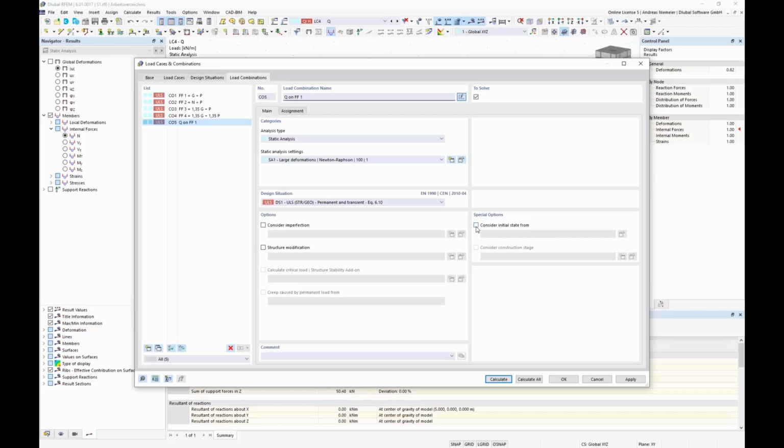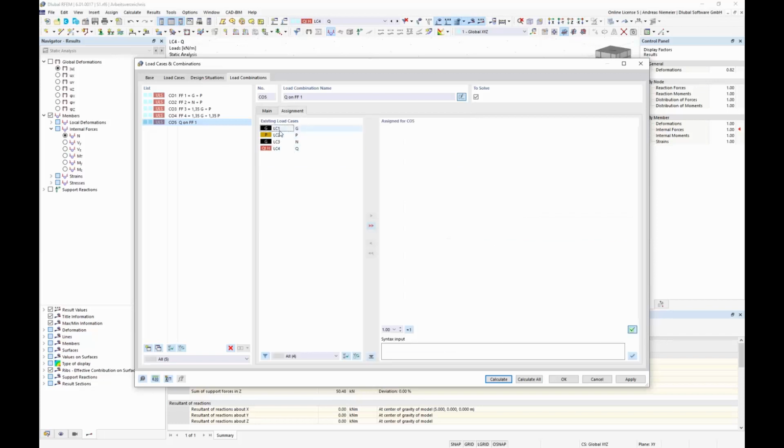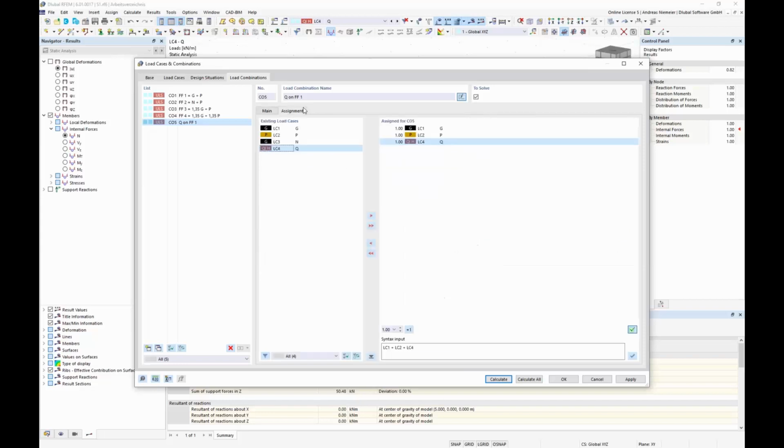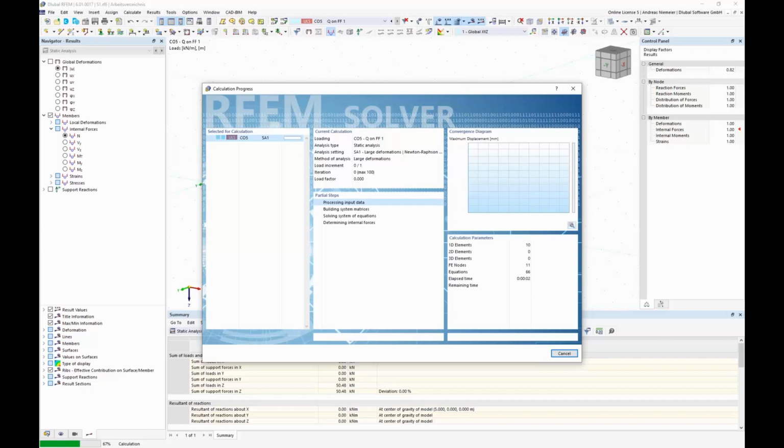So here you specify the shape, for example shape 1. This means we overtake the geometry of mesh and the inner forces, and to get a full set of calculation we apply also the outer loads, form finding loads and the expected, let's say, additional load. And now, according to the situations that we have here defined an initial state as starting shape, the program knows that this is no form finding job and only a pure static analysis job. And let's calculate this and take a look how this is looking.